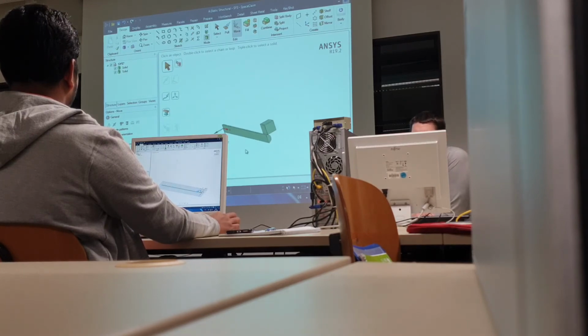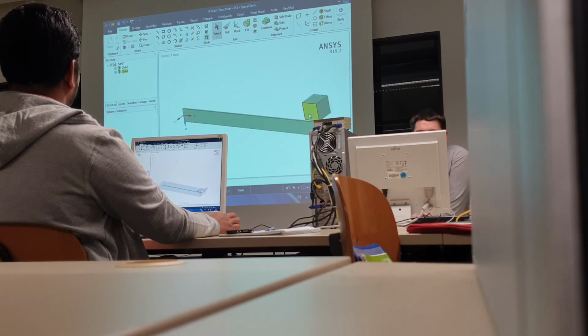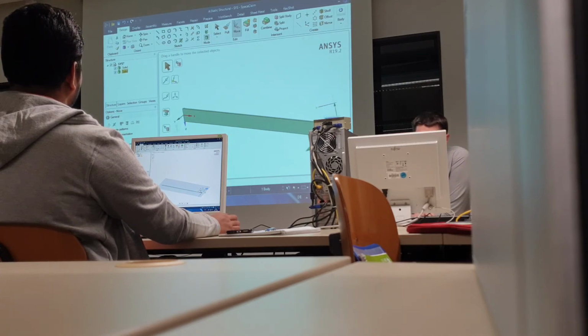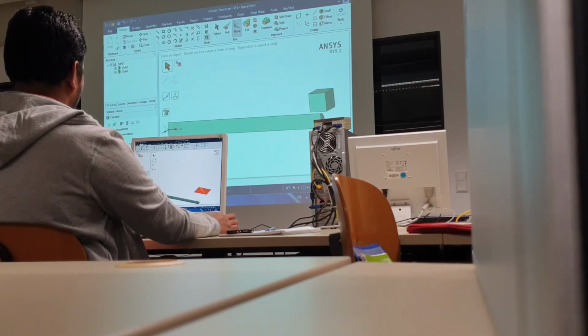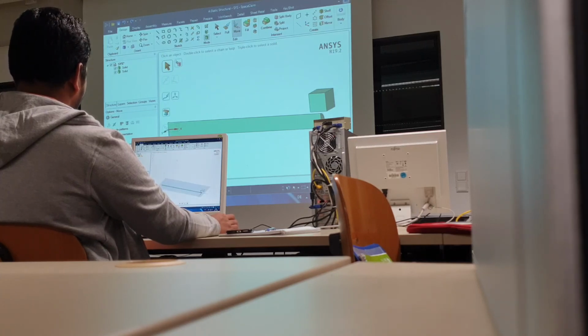Please do it. You can choose the body 3 times, push the mouse button, and then use move. You can choose with shift two lines, and you see how much distance is here down in the region. Distance 1 millimeter. Everybody has to create these 2 parts. Did you do it? 1 millimeter distance between parts. You will see that this distance is important. Try to do 1 millimeter between parts.